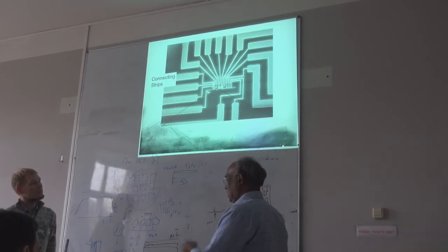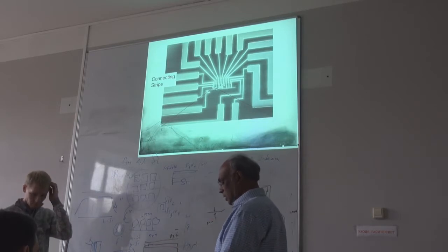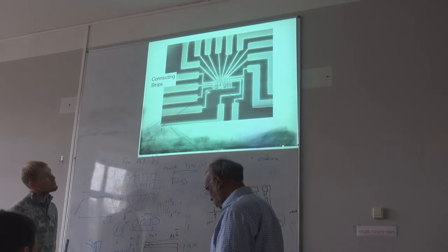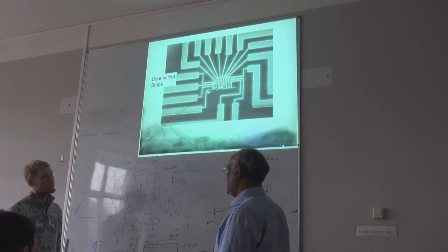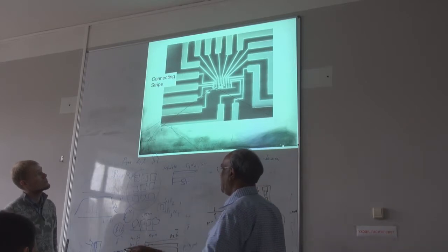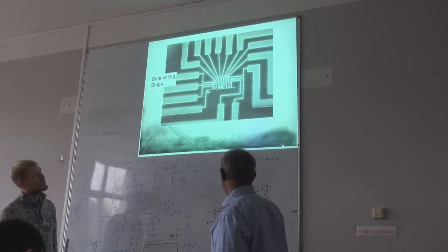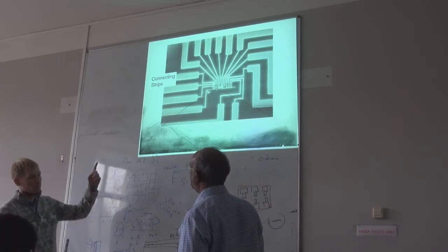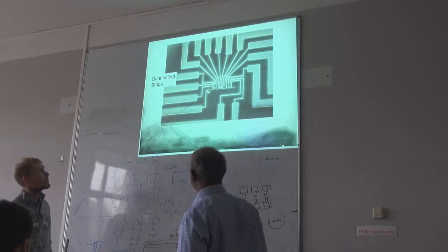Then, the same way, you put your polymer layer, the photoresist, put the mask, and do the developing, etching, then deposit gold and release. Then you get these gold pads here. They are electrodes for measurements. These are all for the measurements.